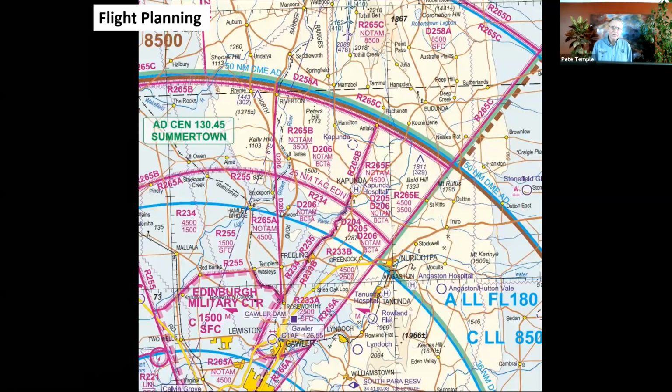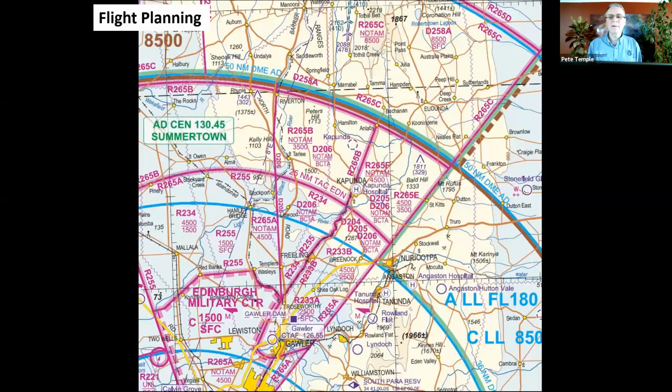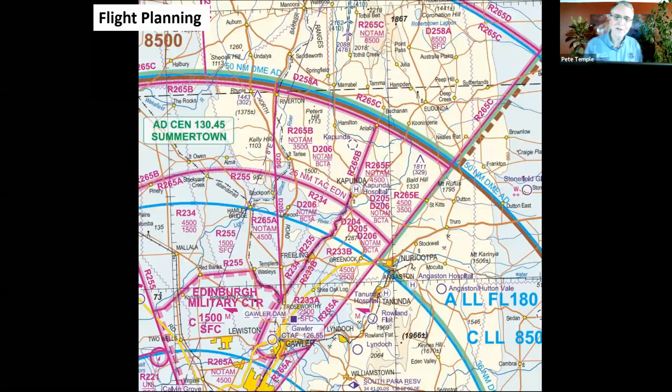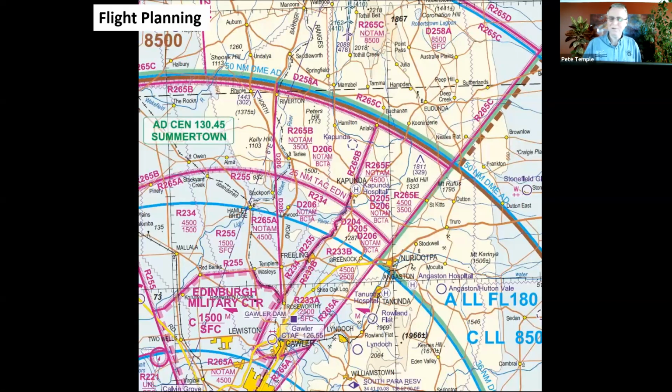It's actually a challenge with distance flying to know when to take off, which actually comes down to the weather modelling, which I'll talk about in a minute. Because if you launch too early, before you know it, you're back on the ground having not found any thermals because they're not there yet, they haven't started yet. If you take off too late, then you've wasted some of the day. And in terms of taking off too early, there are several flights where I've been quite embarrassed, declared 1,000 kilometres and find myself back on the ground after about 5-10 minutes, which is a little bit embarrassing. So it is important to actually get the time to take off as accurate as possible.